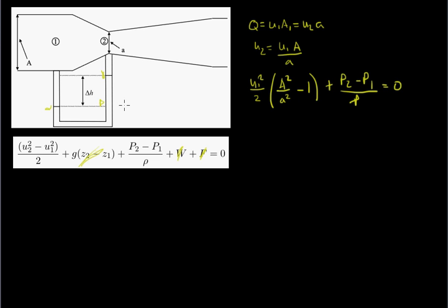So one thing to note is that this is mercury, and mercury has a very, very high density, especially when compared to isopentane. So we can say that rho m is much, much greater than rho. So what that allows us to do is just say that P1 is going to approximately equal our P alpha, and then our P2 is approximately equal to our P gamma.